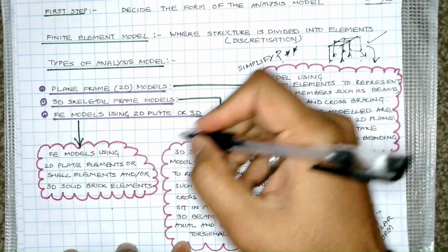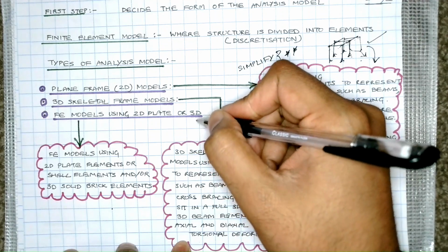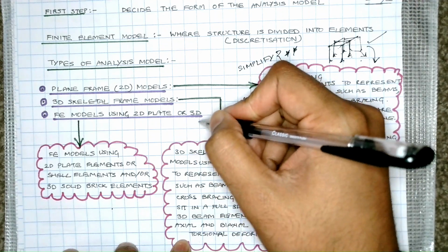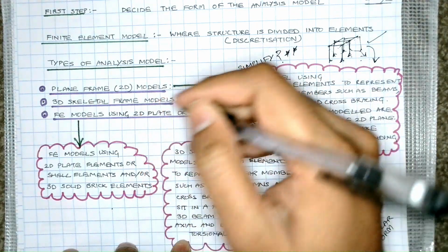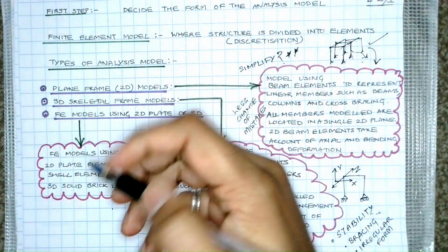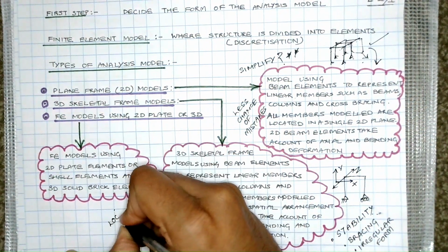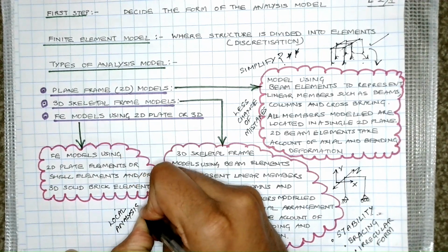I can drop that link on this YouTube video, where I've created a connection in Abaqus, and that actually uses 3D solid elements. Now, why do I have to do that? Because I need to understand the stresses at each point, because each local connection is important. So for the local analysis,